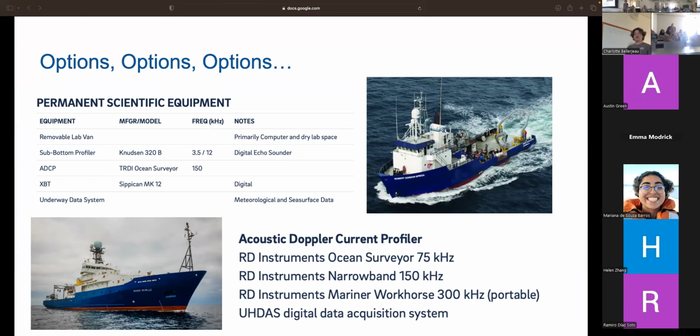But yeah, at some point it's just experience almost. You will learn which instrument to choose for which kind of situation and what kind of needs you have in terms of range, where you are, what platform you are, and what power supply you have. That's another factor. On a remote, self-contained platform, you need to supply battery to it, and ADCPs are quite battery hungry. So there are many different factors to take into account here.